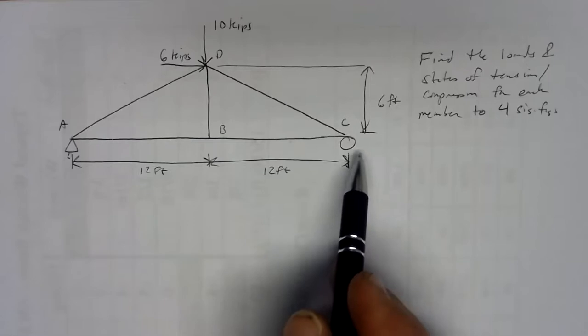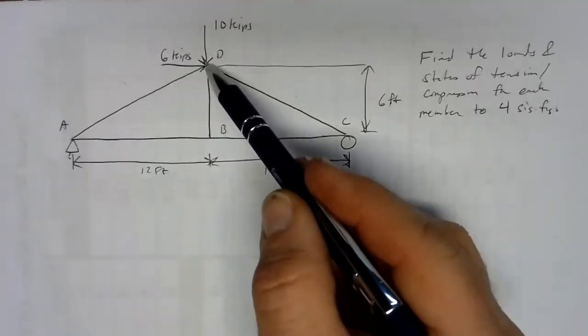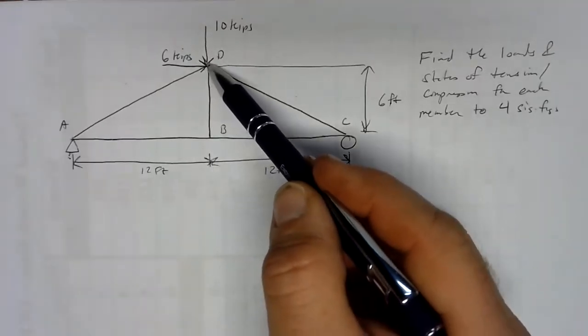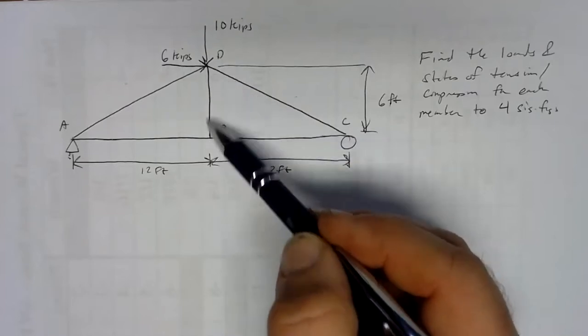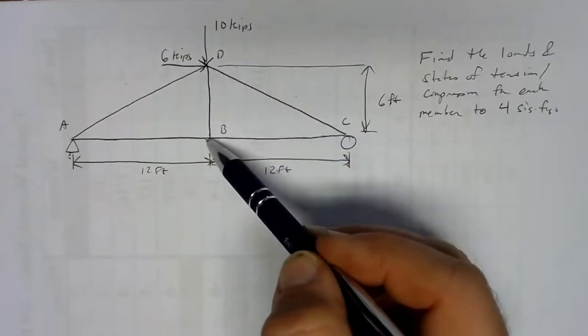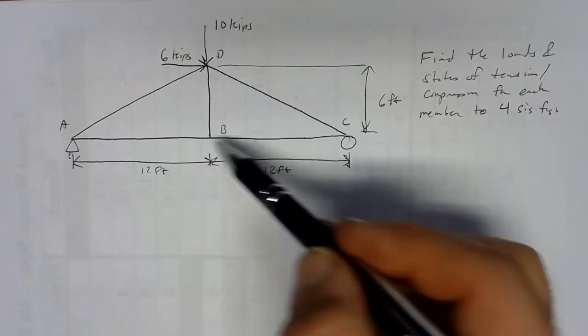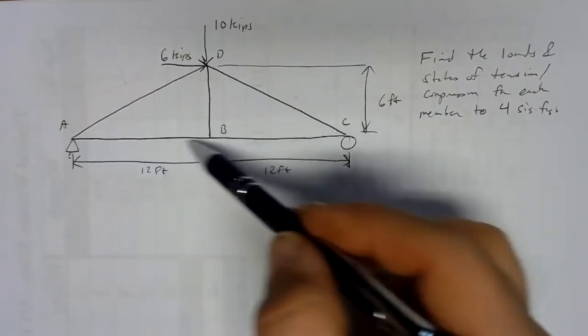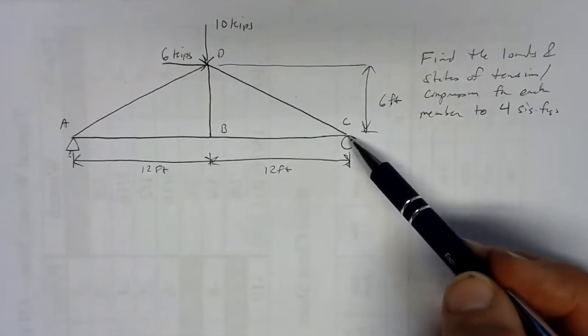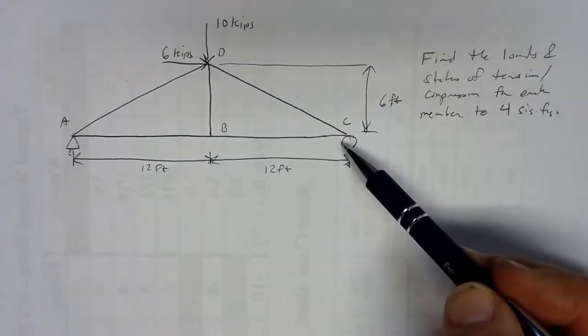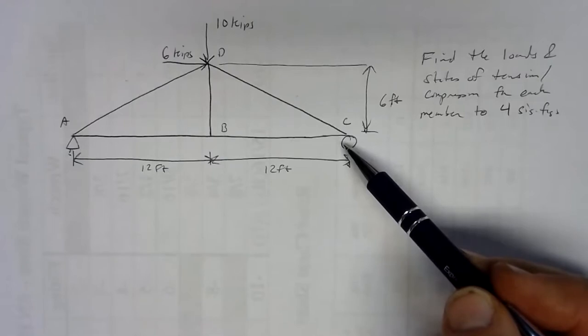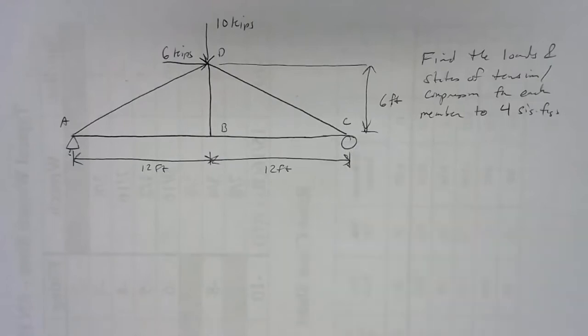It's a 24-foot wide span, and it's got this member dropping down here from the apex to tie right into the middle, so that it can go across the span without this joist sagging too much. It wouldn't meet code today for a 24-foot span using this kind of lumber, but back then people did it pretty routinely.